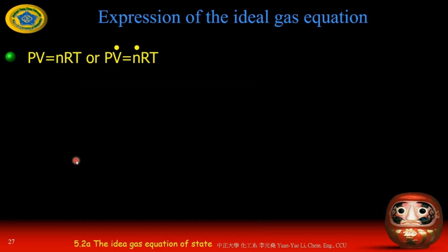Right. So now I want to show you some of the things which you haven't learned in high school. We know PV equals nRT, right? Have you heard about P V-dot equals n-dot RT? The dot means you divide the value by time. That means what? Volumetric flow rate. n-dot means n divided by time, which is the molar flow rate. So we are talking about a continuous process.